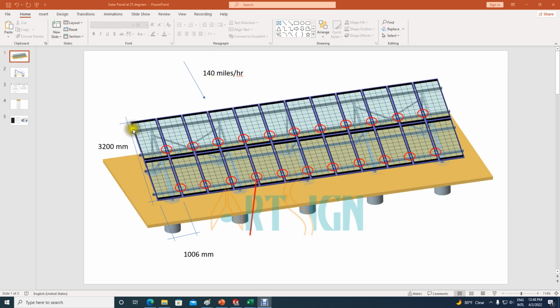Now for the design, he's going to have a length of about 3200 mm on this side and about 1000 mm on this side. For my analysis on SolidWorks for CFD, computational fluid dynamics, I will only analyze 1, 2, 3, 4, up to 4 only. This side here, one third of the total. My machine is not that fast, so analyzing the whole thing and getting the accuracy that I would like will require a small grid, and that will create problems. The system might not be good enough.